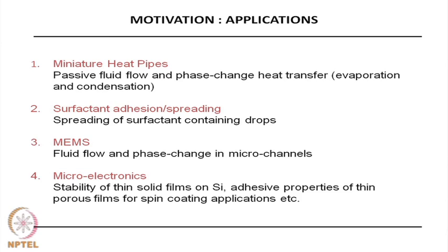So, that is another motivation for the study of thin liquid films. In MEMS and in microfluidics, which involve fluid flow and phase change in microchannels, or the stability of films on substrates such as silicon, or the adhesive properties of thin porous films for spin coating applications, all of these are direct applications of the interfacial phenomena in thin films.